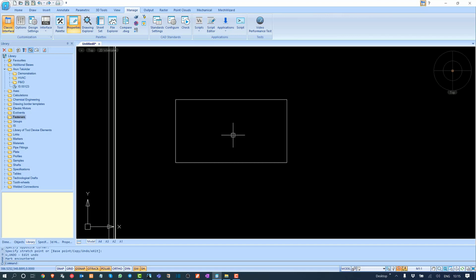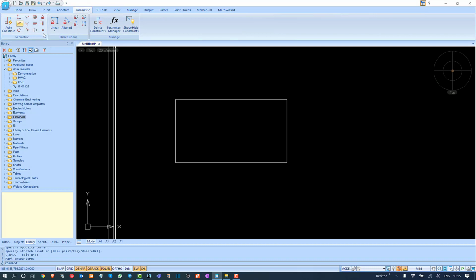But if you use some relations, those parametric functions in nanoCAD Mechanica, to make these rectangular properties intact, you can change the area, but the rectangular properties will never end. So that you can do using the parametric tools. But if you really want to create objects, parts or assemblies, super flexible, that will allow you to create any sort of drafting to represent any object or any part or any assembly, then you need to create the library parts, right?